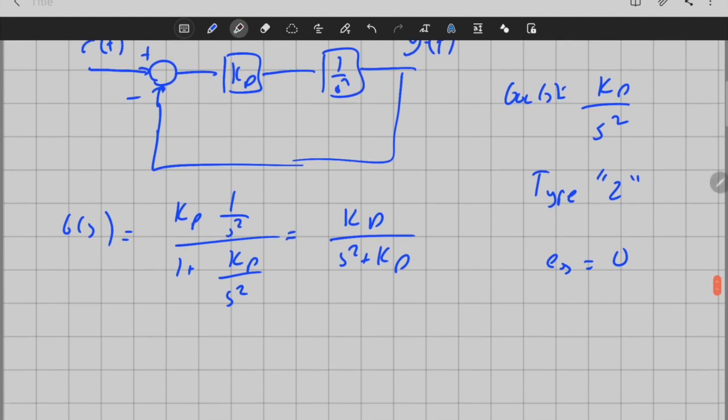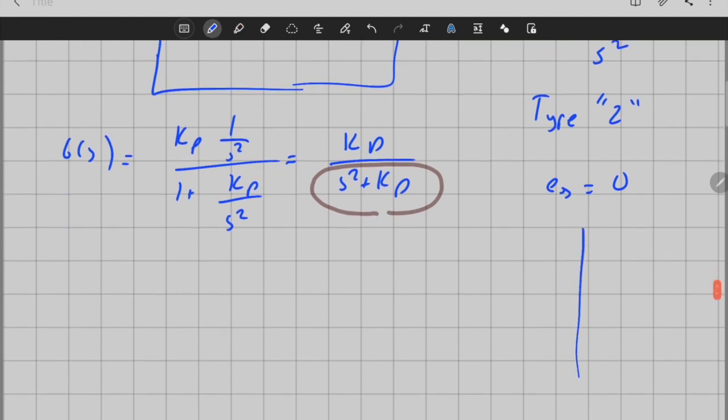What I found is that I have two complex conjugate poles. So I have a pole here and a pole here, which means that my system is BIBO unstable. If I have a BIBO unstable system, it means that the system is not stable, which means that for a constant input, the output may not go to a constant value.